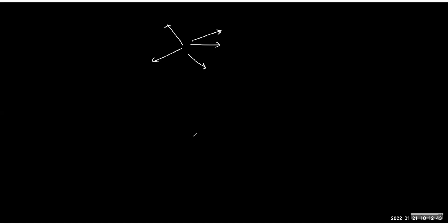So the basic difference between the AC and DC is like scalar and vectors, one dimension and you can say two dimension. Just like you cannot add two-dimensional things as scalars, you cannot just add the value. You have to add the value with direction, correct? And that is why the AC circuits are a bit difficult to solve. But you can solve very easily if you understand the vector notation. Okay. So you can exactly do the same calculation like taking the component and adding the value, squaring and adding to get the net value, and so on. So AC is exactly like a vector.